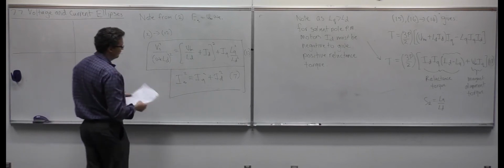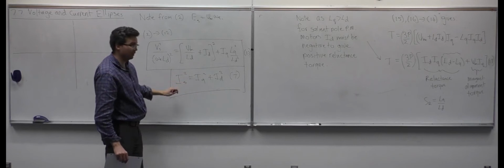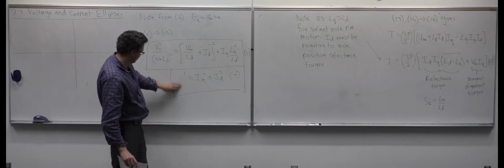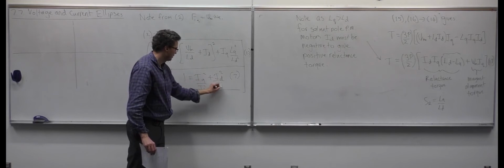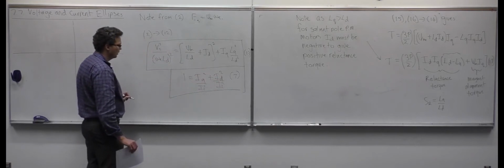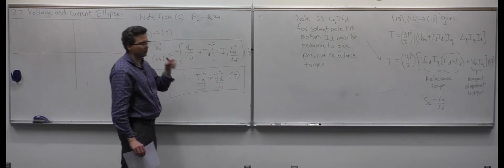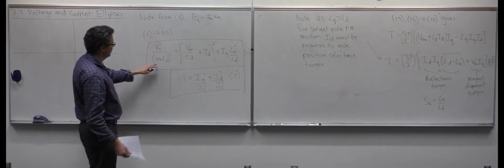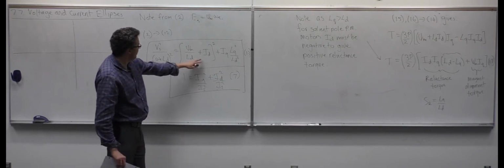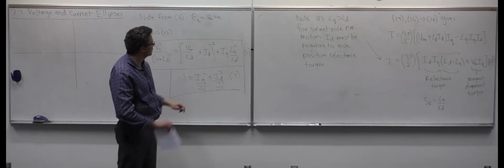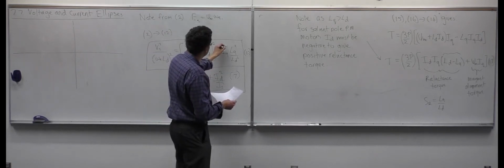So this one is a circle because, if you remember from circle theory, you can divide this by IS squared, and that gives you a circle with a magnitude of IS squared. But on this one it's more complicated because we have an ID and an IQ. I think there's a squared term missing here, right?